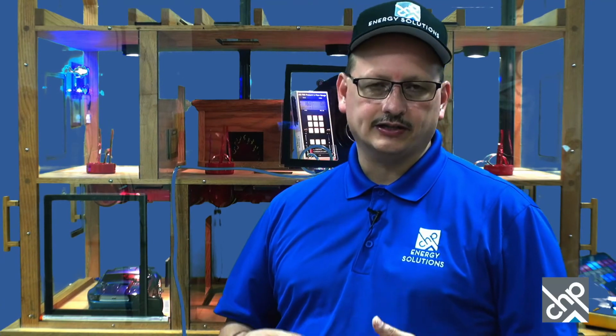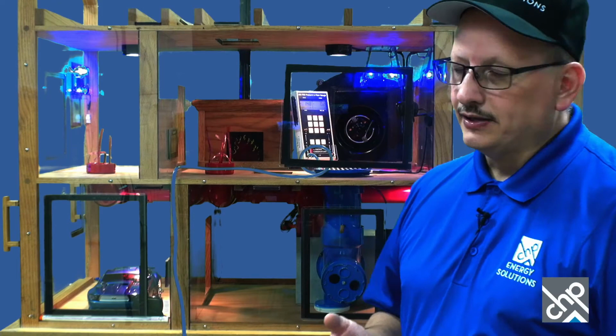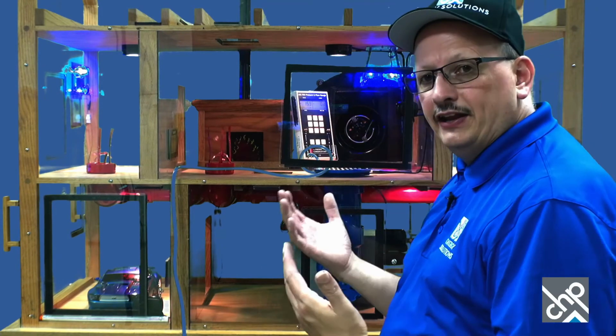If you had a combustion appliance, like a water heater in this area, that's when you would fire it up and do your combustion safety test, do your spillage test first. If it passes spillage, depending on what standard you're using, if you're using BPI 1200, you continue to test even if it fails spillage, as long as you're below 70 parts per million in your ambient air for carbon monoxide. That's in the ambient, and then of course you check your CO in the unit itself, and if you want to do efficiency, you can do that as well for a water heater, those types of things.